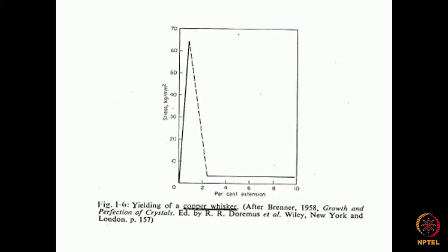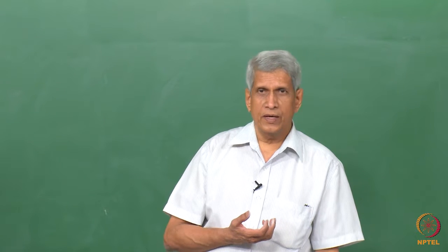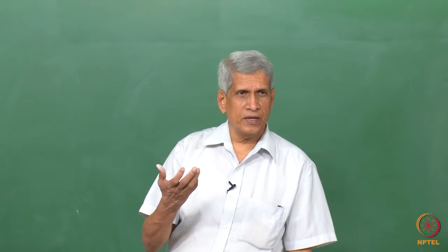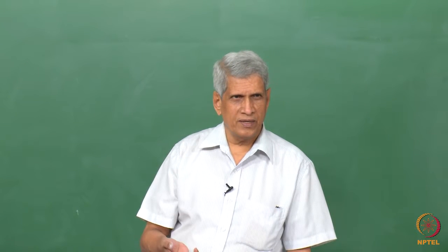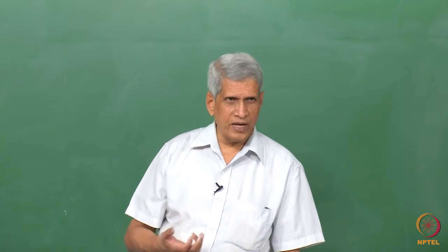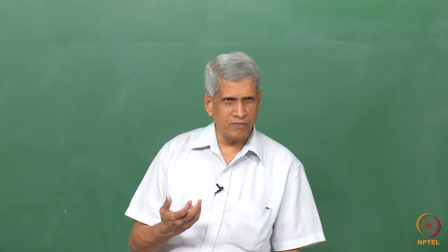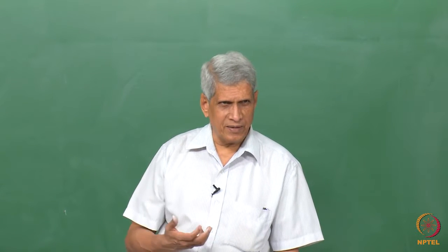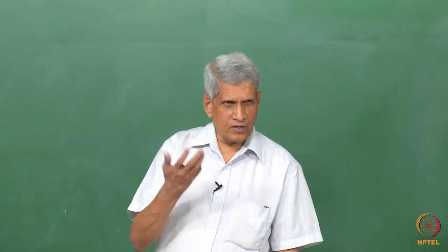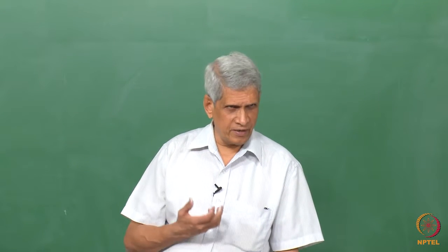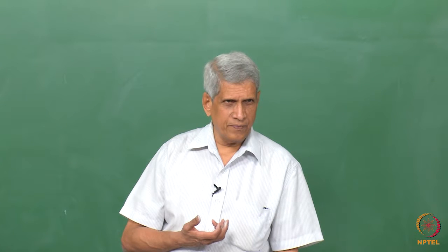Okay, the entropy term is the one which minimizes the total energy. So finally, it is between the energy which is required for the defect to be formed and the configurational entropy. The net one decides whether there is going to be a net increase or decrease. That will decide whether it is an equilibrium defect or not. In the case of vacancies, there is a reduction in energy.